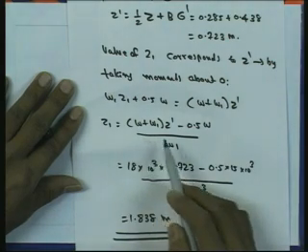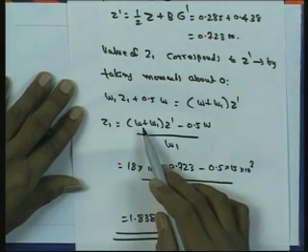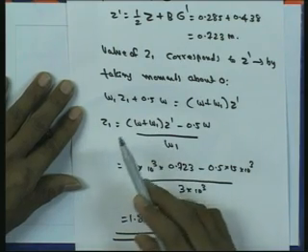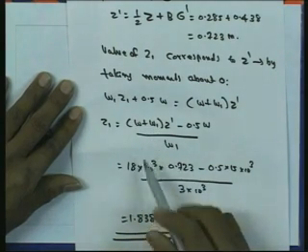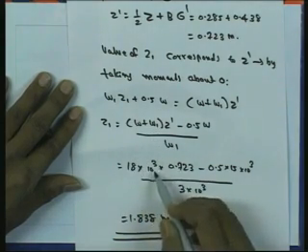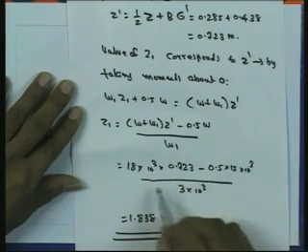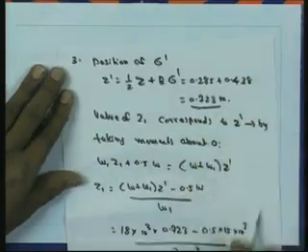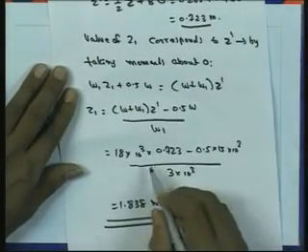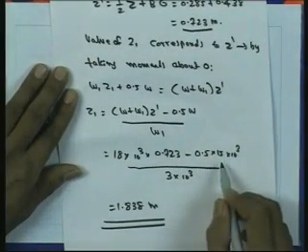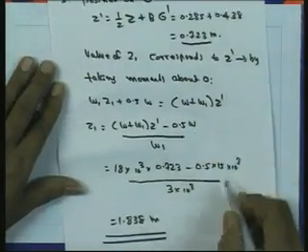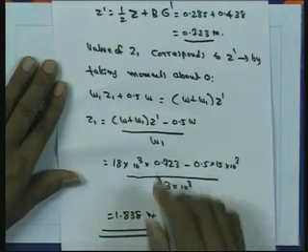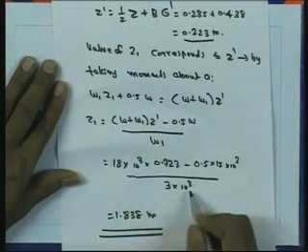Here in this case the weight of the buoy is 15 kilonewton and the extra load placed is 3 kilonewton. So it is 18 into 10 to the power 3 Newton, multiplied by Z dash, which we determined as 0.723 meter, minus 0.5 into 15 into 10 to the power 3, divided by W1, the extra load, 3 into 10 to the power 3.